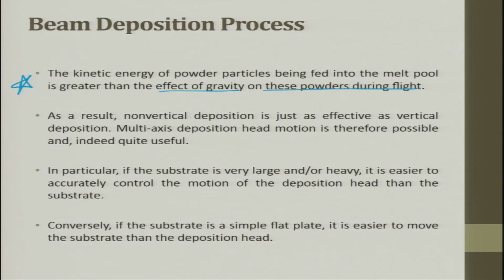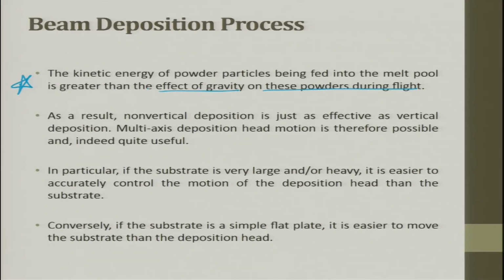Okay. So, this makes sure that it does not create, see, there is a buoyancy which comes. Because of this buoyancy in the melt pool, there is a density difference, so the material can be moved out. But on top of it, the kinetic energy of the powder particle just hits it and then starts moving it. As a result, non-vertical deposition is just as effective as vertical deposition. Very important point. Multi-axis deposition head motion is therefore possible, and indeed quite useful.